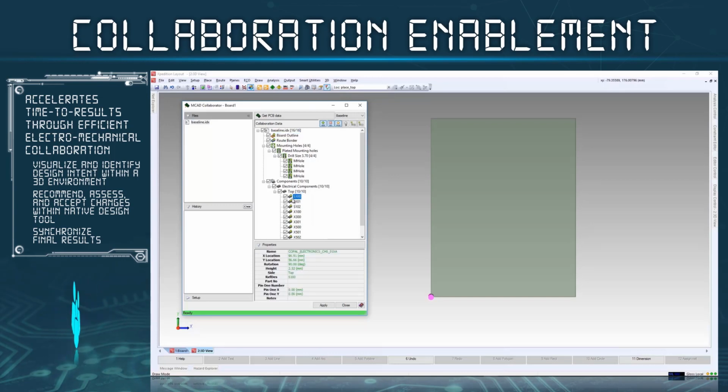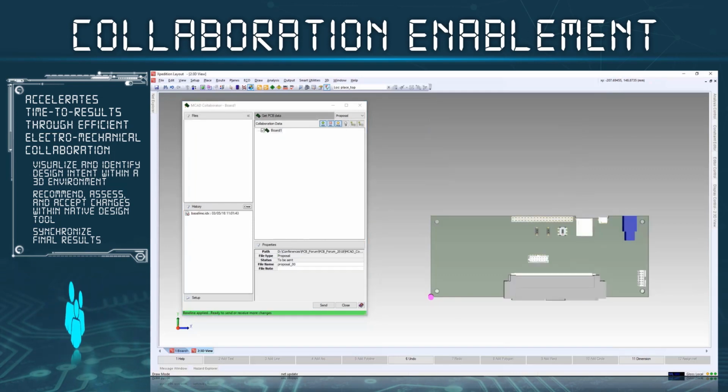After selecting the baseline object from the file selection area, you are presented with all the objects that will be created or placed in the PCB. For further assistance with reviewing content, you can select an item and see more details. With Highlight active, you can make this object appear in the design for graphical preview.